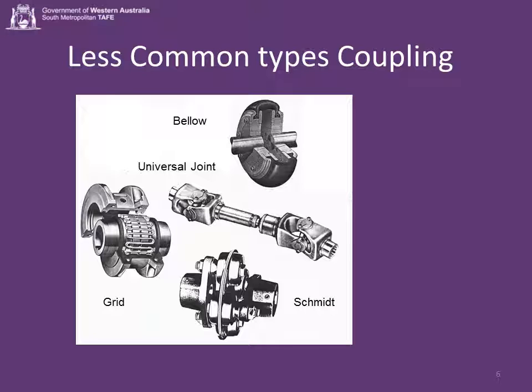Now, according to Wikipedia, the advantage of direct coupling is that it increases efficiency. We've not got wasted energy due to friction from belts, chains and gearboxes. It reduces noise, being a simpler device, has a longer lifetime, there's fewer moving parts, less prone to failure, once again fewer moving parts. It can deliver high torque at low RPM. It's a stiffer system, so hysteresis and backlash are all minimized.